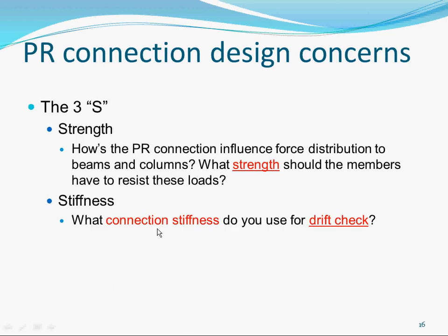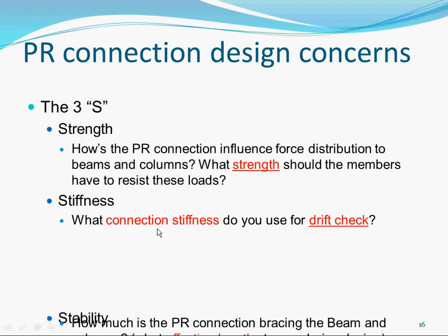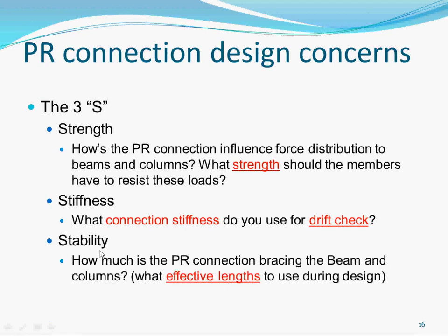Stiffness. What connection stiffness do you use for drift check? And the stability. Stability is related to what is your effective length to use during design for your beam and columns. So let's see how we address some of these in our connection.